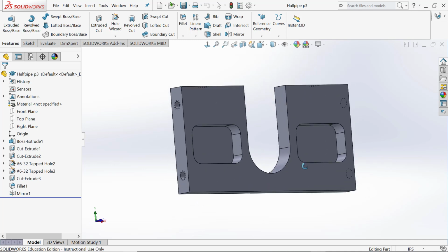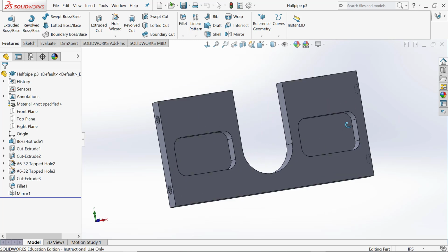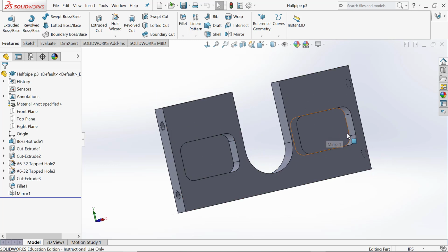This is not uncommon at all when you make a part for a particular purpose. They want to save on material or they want to save on weight, perhaps for shipping purposes or whatever. So we're going to make these indents here, these cuts, to sort of lighten the part, make it less heavy, use less material. Notice they do not go through all those. So when we do the cut on these, we're going to have to do an end condition of offset from surface. Perhaps you remember that from when we did the cooler part. So we're going to do something like that.